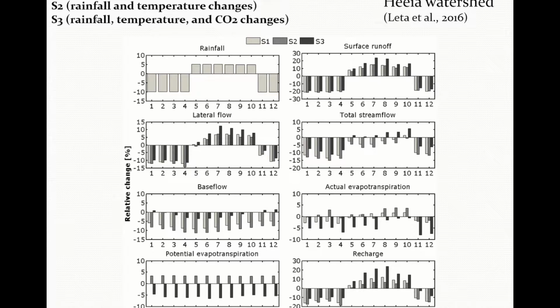And we consider different cases, like here, rainfall change only, rainfall and temperature change, and rainfall, temperature and CO2 changes. It's more realistic to consider all the three variables because there is intercorrelation or cross-correlation between them. So this is good for planning and management of resources. For example, you can address flooding here, you can assess recharge, future needs for drying conditions, for example, or the potential shortages.